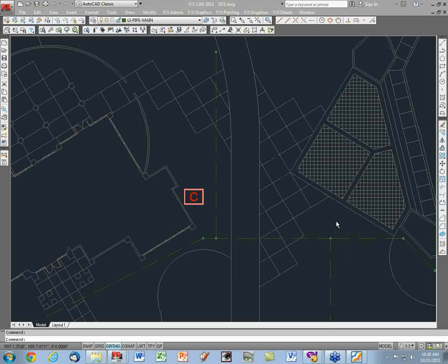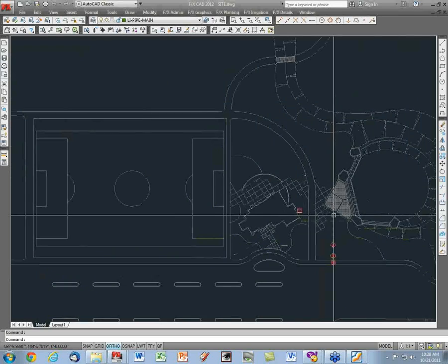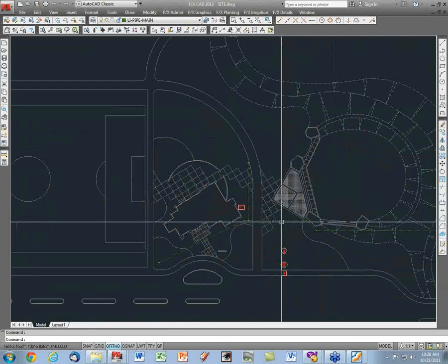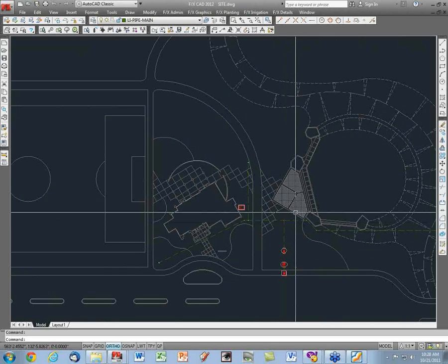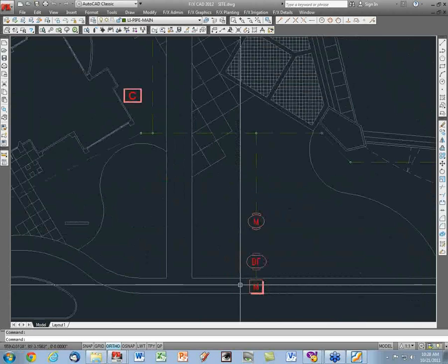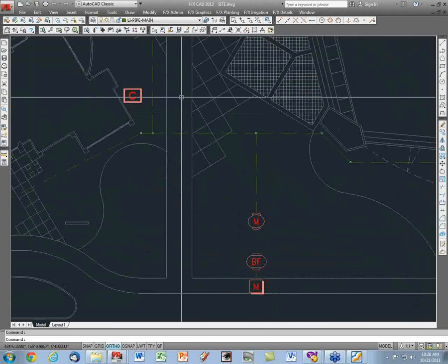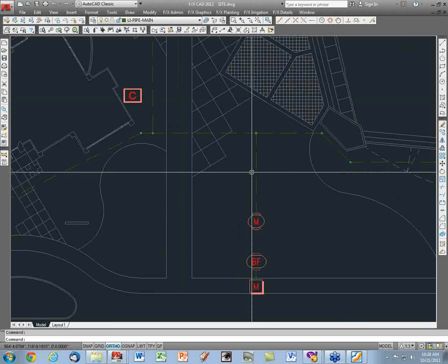What I want to show you, I think is interesting, is 5 different ways to use these. 5 different kind of situations that could arise. The first one is the most simple. I have one point of connection. I got a meter with a backflow device. I have a master valve. Somewhere I have a controller, and of course this main line is running around.